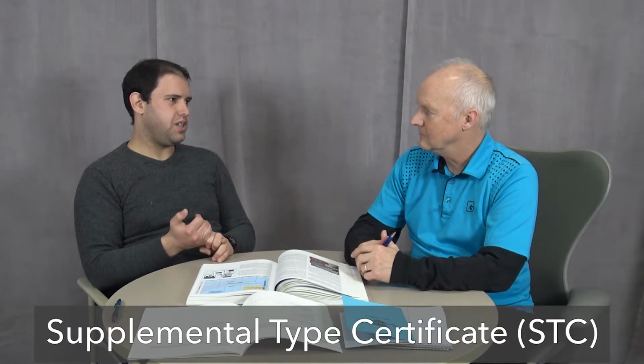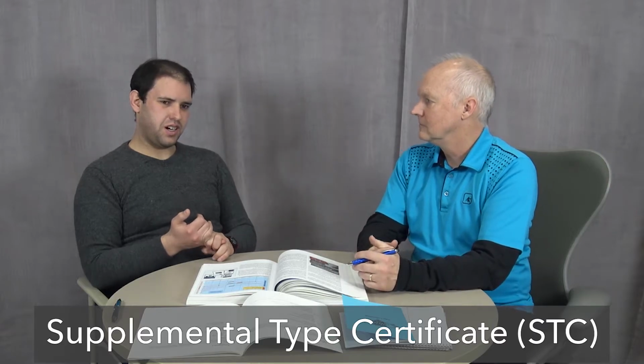So if you wanted to, for example, put a larger engine, in the case of the Chief, there is no option for a larger engine. Right. You would need what's called a supplemental type certificate, or an STC, so that each aircraft is certified by the FAA under what's called a type certificate. So that's a certificate that's issued to the manufacturer by the FAA that says you have the authority to build an airplane to this design at this factory, and here are all of the... Well, at this factory, it would actually be a production certificate, so that's slightly different.